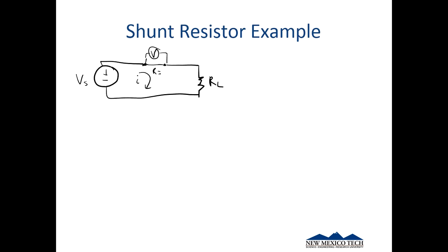And I know that this resistor is 1/1000th of an ohm. We've got some copper bar there. Sometimes you'll see that. It'll be a copper bar or a copper piece of pipe or whatever. We can say that our measured voltage, we know that because we're measuring it with this meter here, and we know our resistance, because that's why it's a shunt resistor, we know that resistance. So based on that, we can find our I.